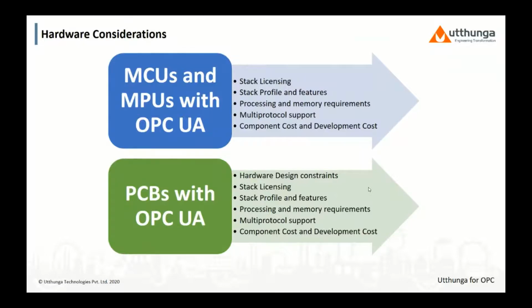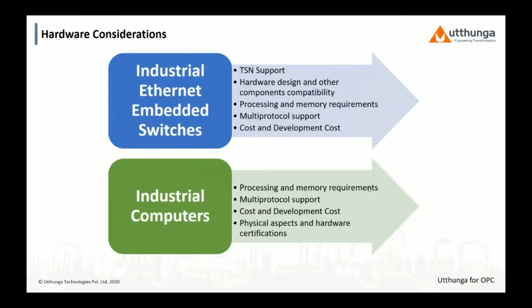do not work well to enable OPC on existing products. These are for new products. In addition to the stack and the MCUs, there are industrial Ethernet based embedded switches available from different vendors, where these switches come with TSN support and also protocol specific firmware for that switch based on what kind of data they're publishing. So you can see how having such a switch would accelerate your overall product development and will yield better performance with respect to the network communications.